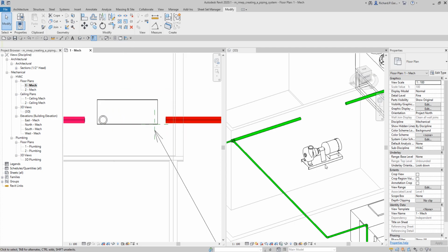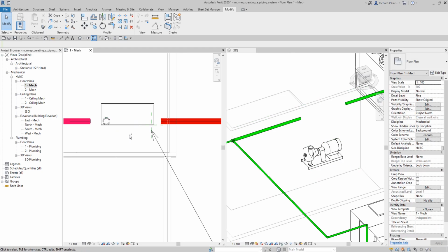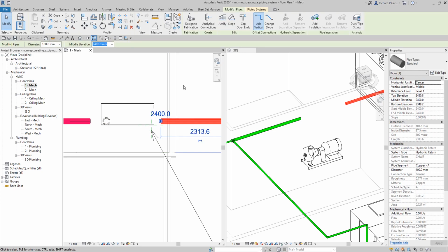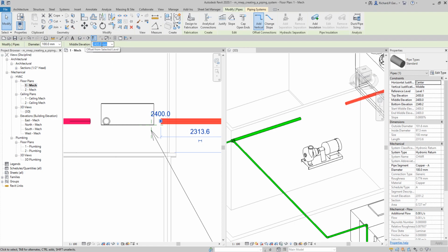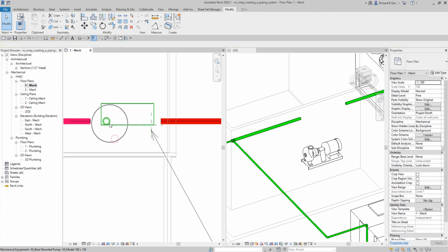You can actually do that here in the 3D view, or you can also do that here in the plan view, as long as you know the elevation. Or you can also go to your section view. You can create a section here, and then from the section you can create the pipe. In the plan view, as long as you know the elevation of the pipe where you want to connect, for example, we want to connect the pipe that we will be generating from here to this pipe. You just click this pipe, and then you can see the elevation already. So you can create it here from the plan view, but if you want, you can create a section.